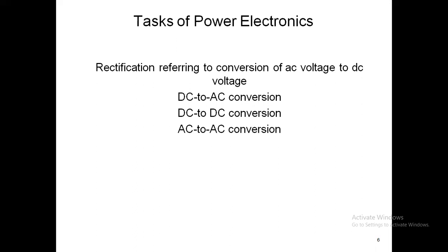You have to decide the switching frequency and the duty ratio for that device, and the value of the capacitor and the inductance on the basis of the voltage and current ripple. So voltage ripple is decided by the rating of the capacitor. It restricts the voltage ripple, so it is connected across the output so that the voltage ripple across the output does not get violated.